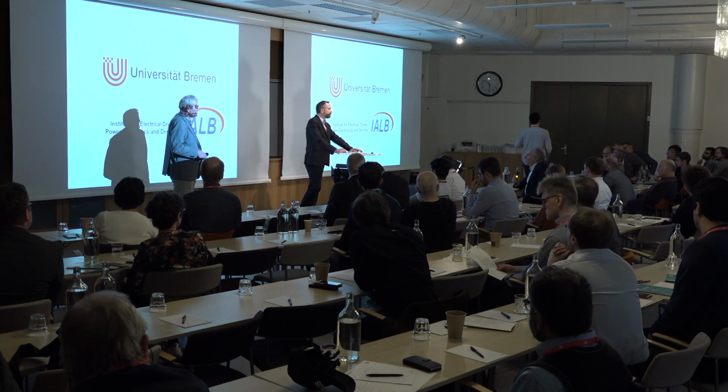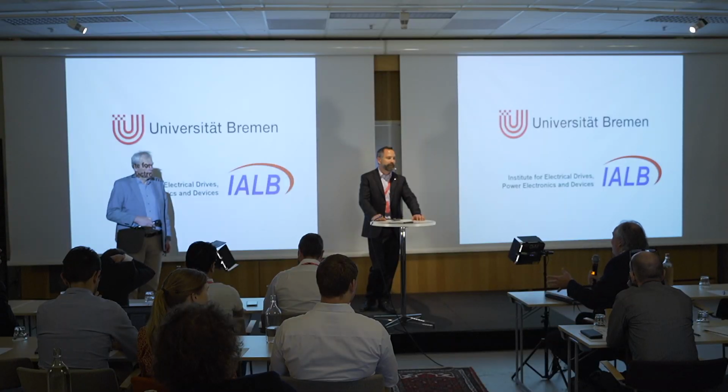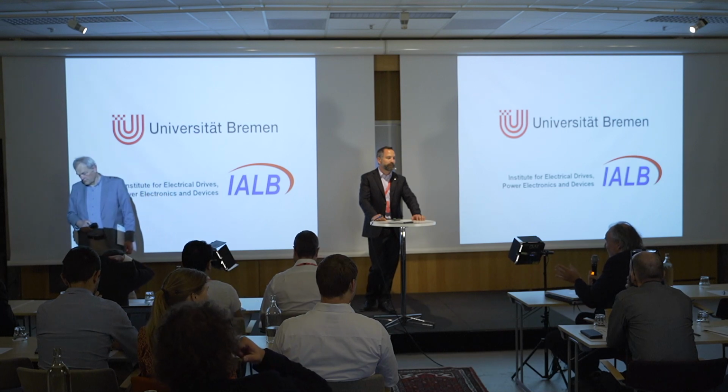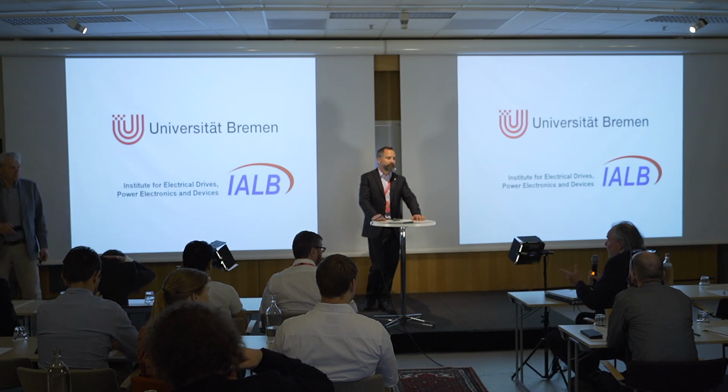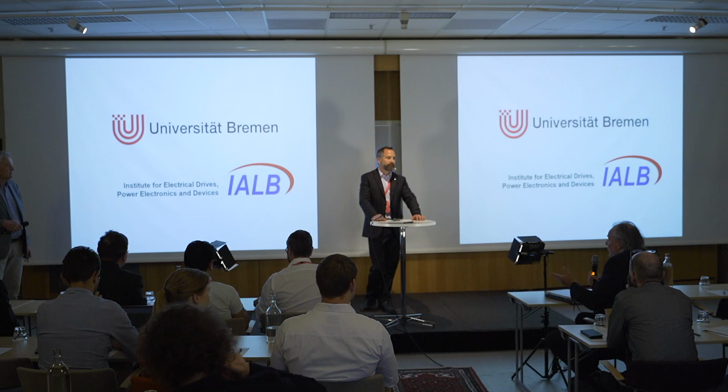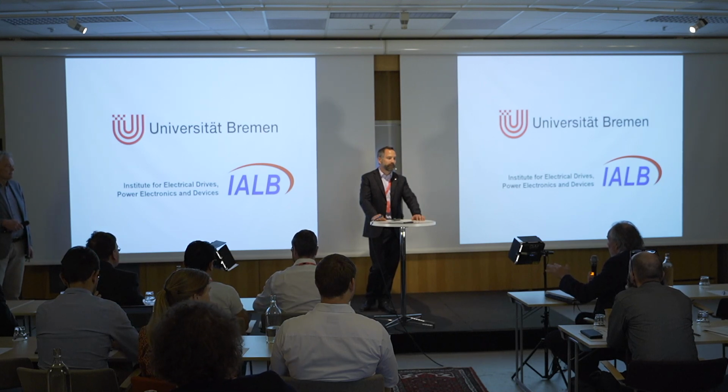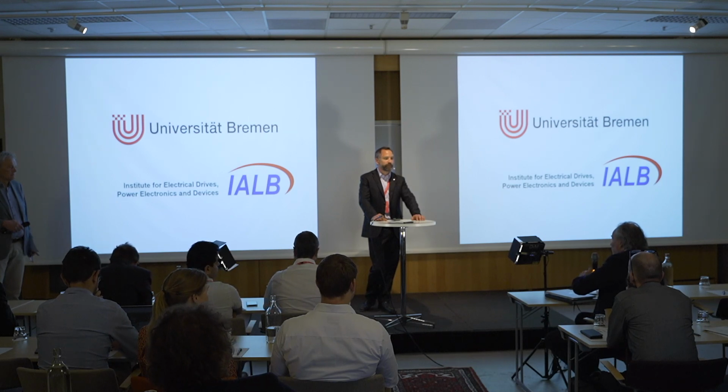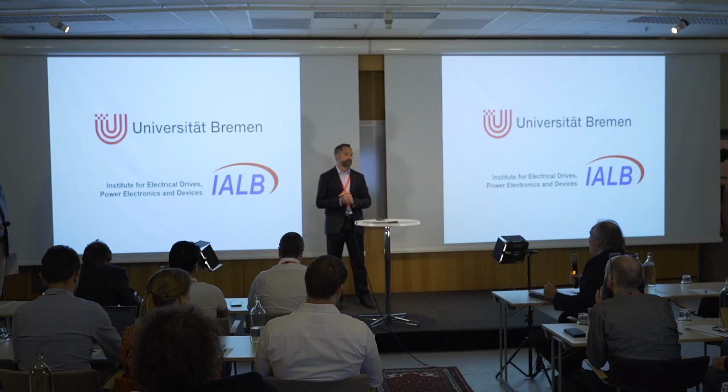So I'm of course curious on the root causes that different silicon carbide MOSFETs in the same packaging line behave so differently. Do you expect this more on the material side, like metallization schemes to play a role, or are these really some topics of the design, like for example, topology differences in height towards the edge termination and so on? So what do you suspect, and what tests are you doing in the future?